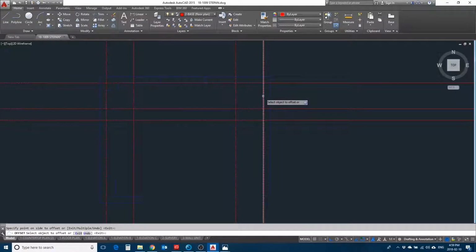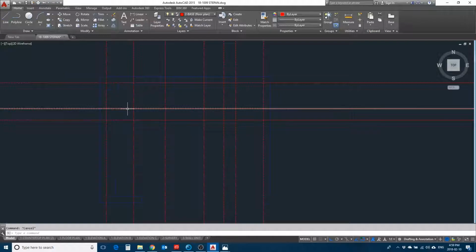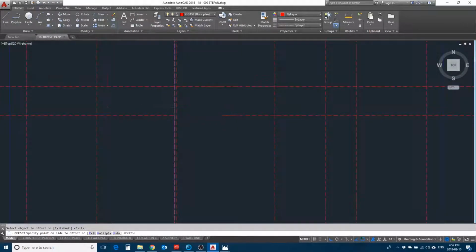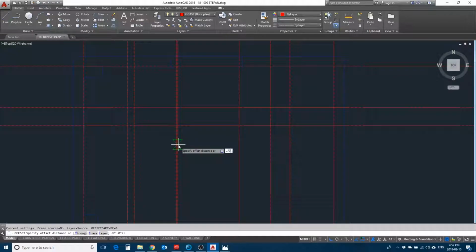I'm gonna start from this corner, and then looking at my drawing, the next cabinet is 18, offset 18. Then we have a 31-inch sink cabinet. Again, this is all looking, and that doesn't look like it fits, so offset 35. It's a 35-inch sink cabinet. That looks somewhat off-center. Then we have a 0.75 panel for the dishwasher and 24-inch space. Dishwashers are always 24. So we press O, enter, 0.75, click on the line and offset.